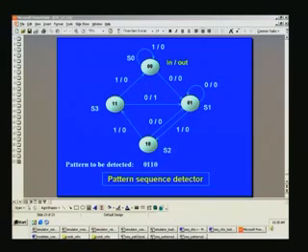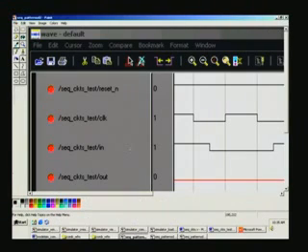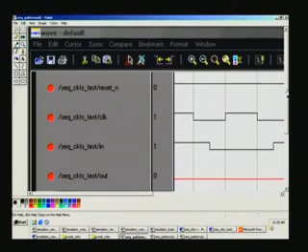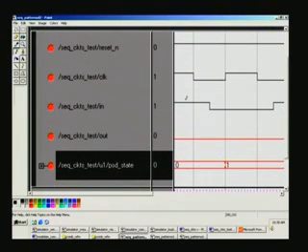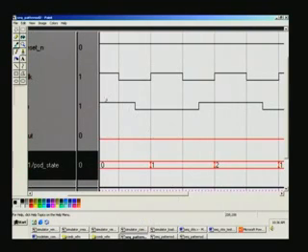Now next, we have the second set coming over here, and you can see from state 0 we are moving on to state 1. Let us see what happened in the meanwhile. First, the input is now 0. Earlier it was 1. Now the very first pattern coming is 0, and at every clock transition it is being reckoned.